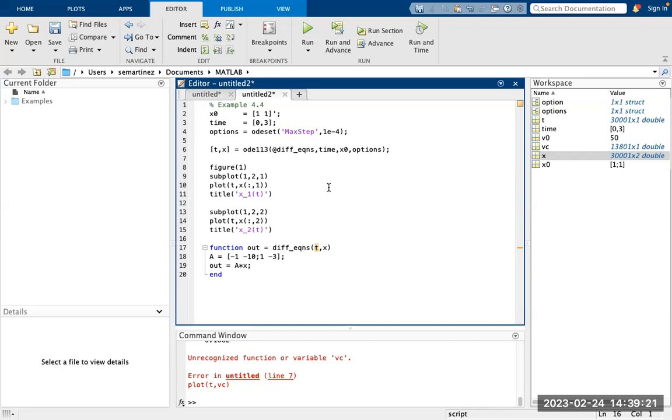From this one, you're going to get a set of, let's say, 12, I think it's 12 equations to represent the generator, the exciter, which is one of the controllers, and the governor, which is the turbine controller. So you're going to have 10 differential equations here. For any synchronous generator, you're going to have 10 differential equations. If you have 10 synchronous generators, you're going to have 100 differential equations.